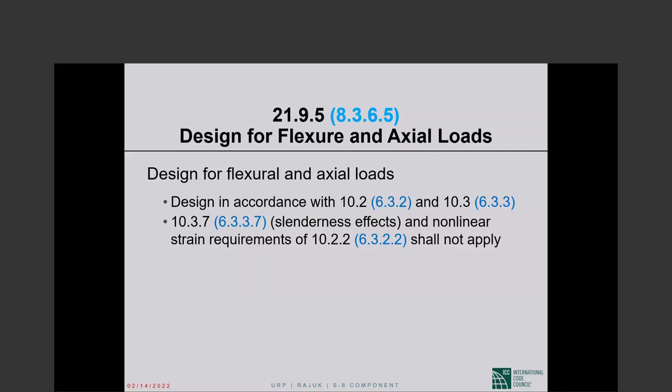The columns at the end and the web are constructed at the same time. Anyway, 94 UBC said, for the purposes of designing for flexion and axial load, a shear wall is no different from a column. The entire cross-section is effective, the flange as well as the web.